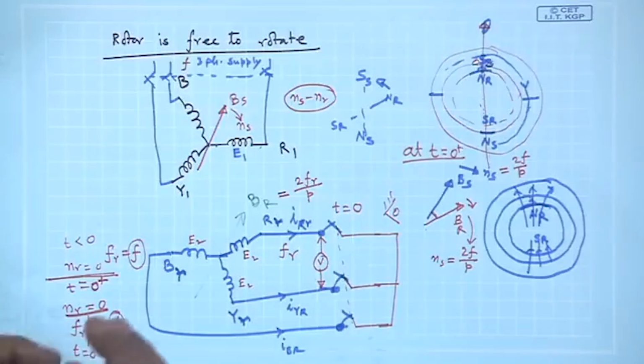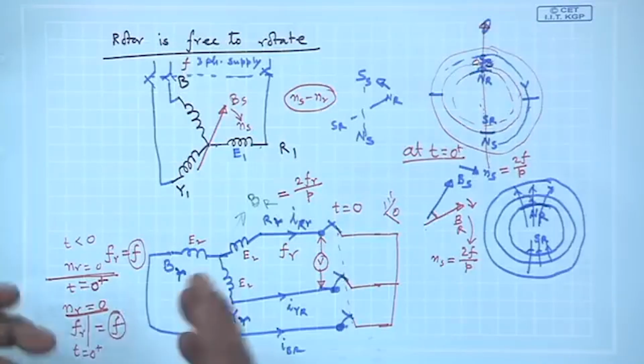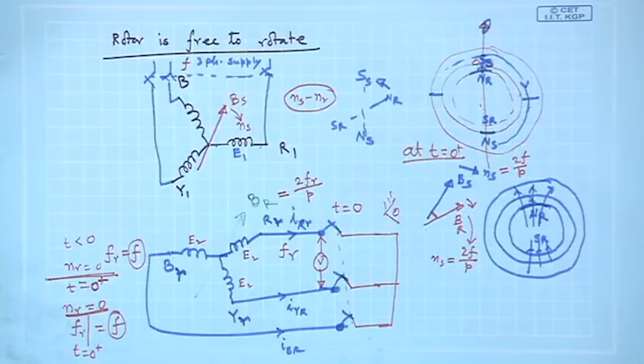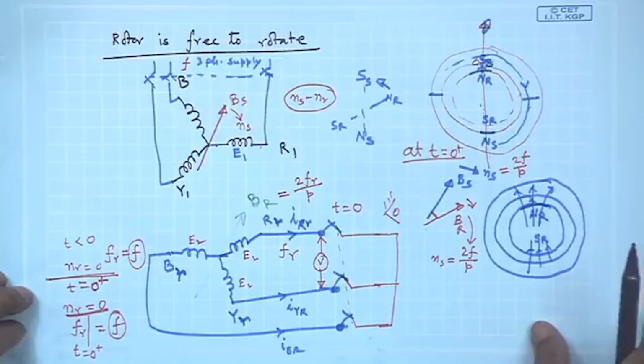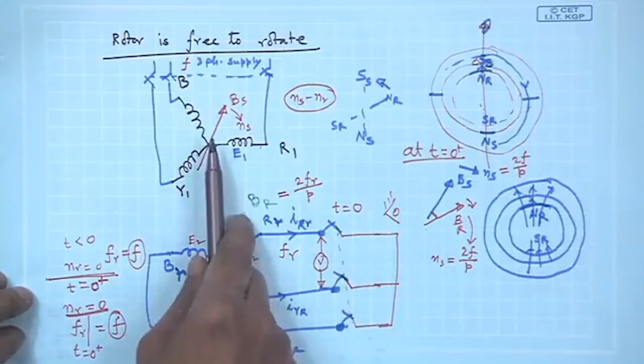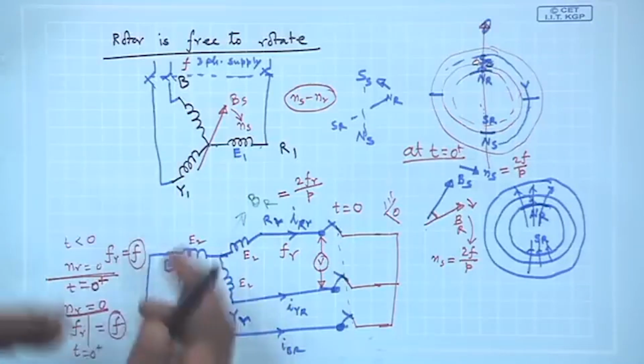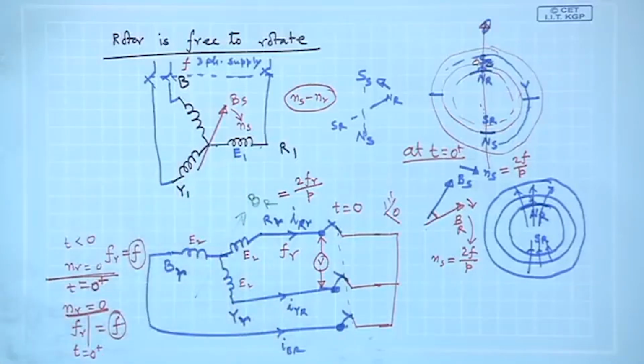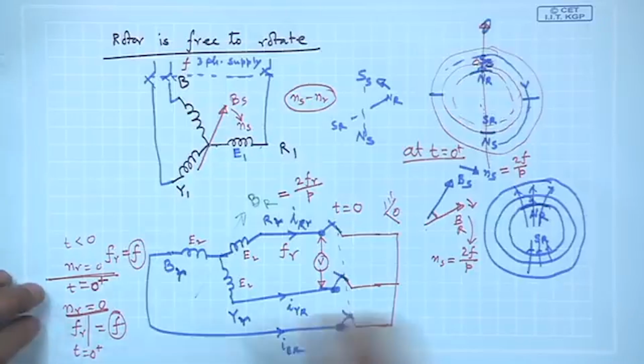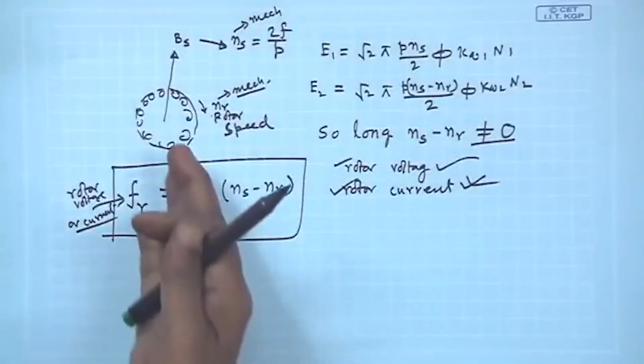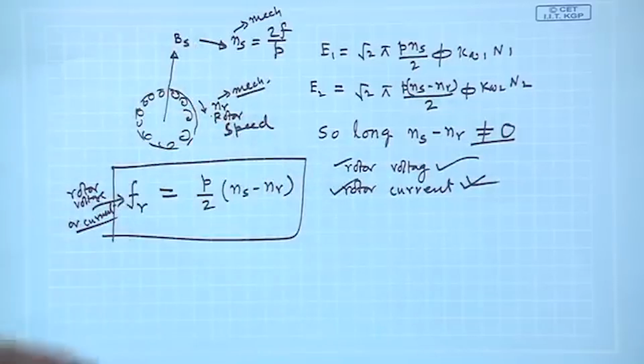Therefore, it is expected there will be a constant angle between these two, and perhaps a constant torque will persist, and rotor will accelerate in the same direction as that of the stator field, because only in this direction will the cause for which the rotor currents or rotor voltages are due reduce. That is what Lenz's law tells us.